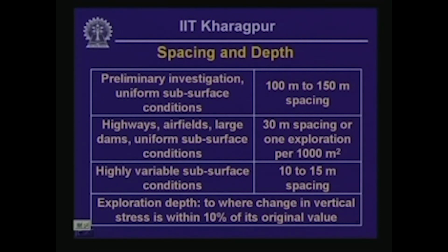It is quite obvious that if the investigation is for deciding the preliminary alignment of a linear facility such as a highway or a railway, then the investigation can be carried out at a relatively wider spacing in comparison with the investigation undertaken for a detailed design project of the same facility.